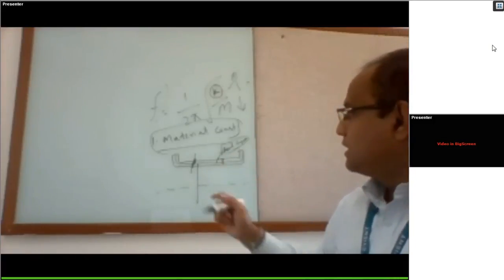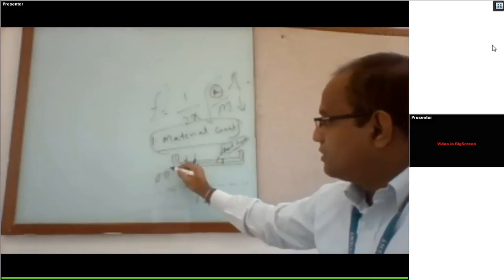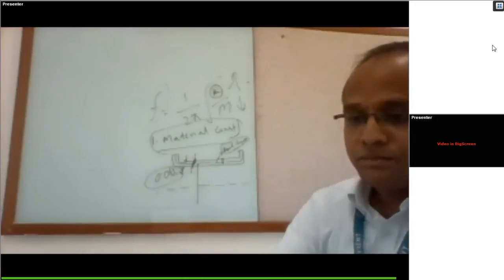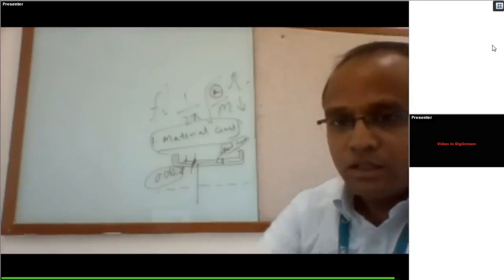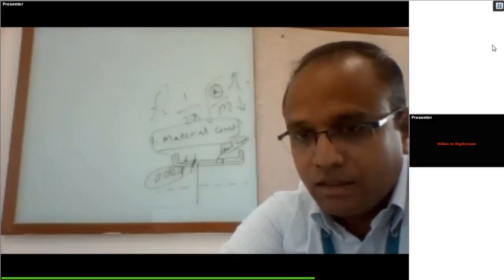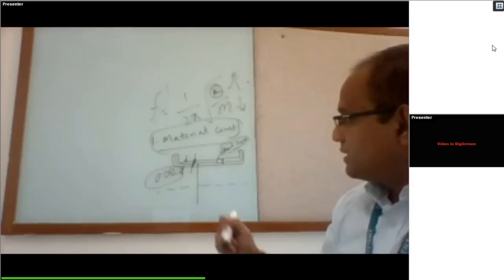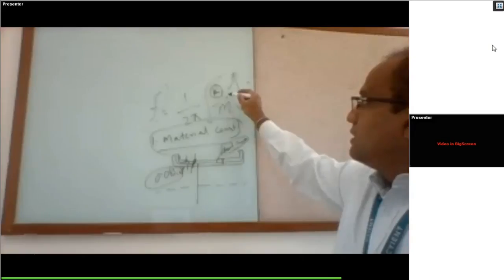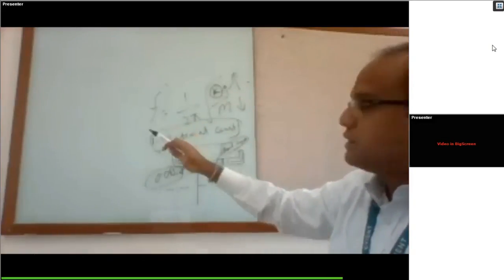The current thickness is 0.085 inch. This is the baseline. So the case wall thickness is 0.085 inch, and we got 137 hertz. Now our option is to increase the thickness, so we need to see whether, as thickness increases, the frequency will increase or not.